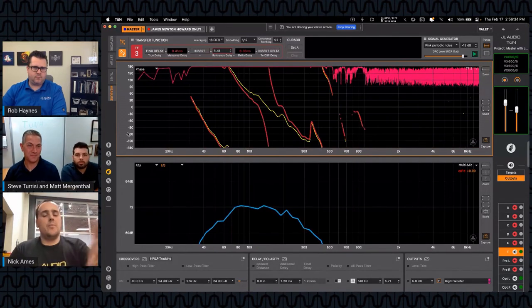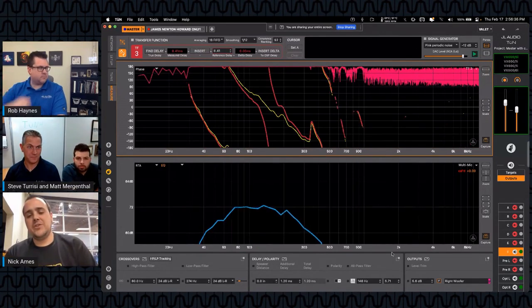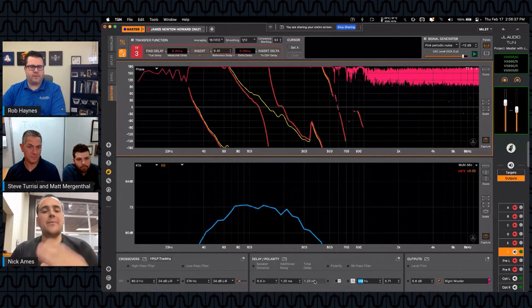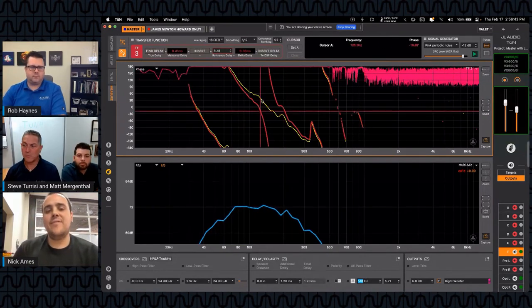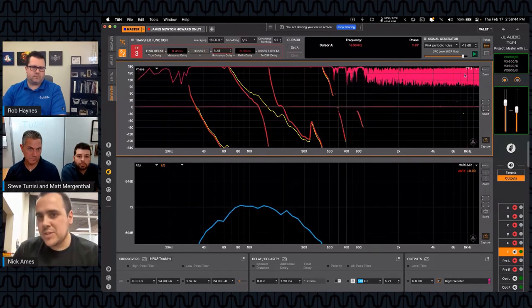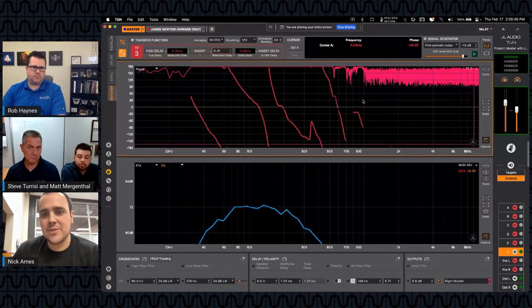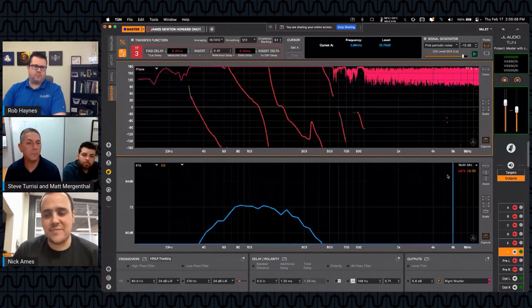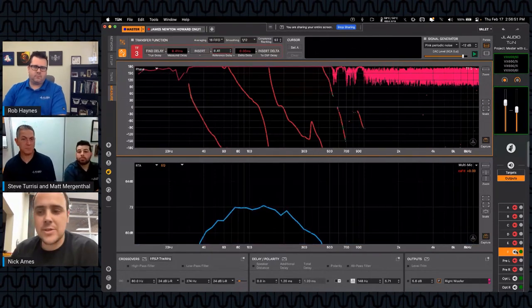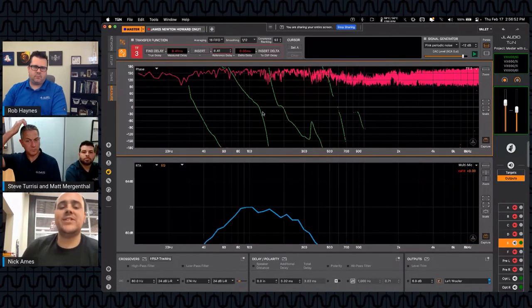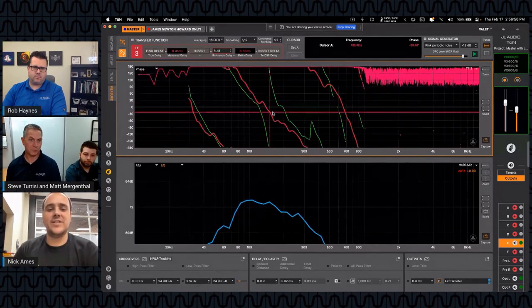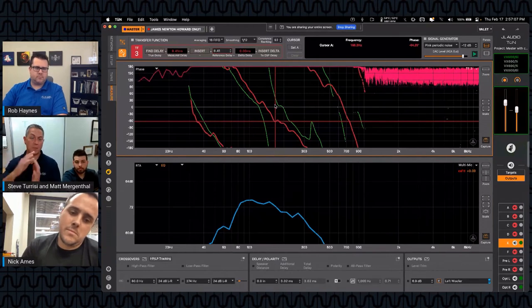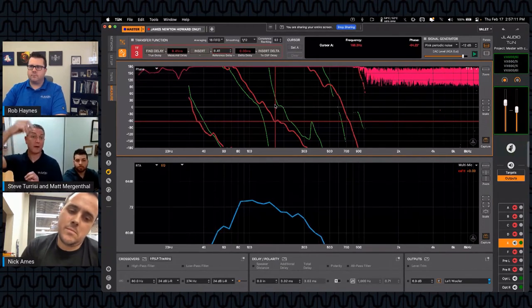So sometimes what I just induced on purpose electrically will be happening acoustically. And so what'll happen sometimes is you'll have this acoustically on one speaker, right? Let me hide that capture. And so now we'll capture this as if that were our real acoustic reality. And then you'll have this on the other side that, see, doesn't have that effect right here. It doesn't have that. And you can see that the alignment at those frequencies is about 180 degrees out.